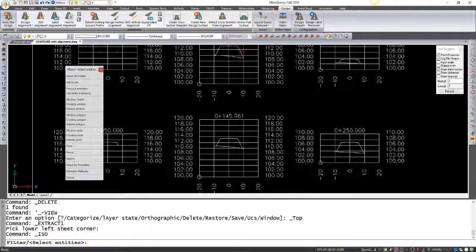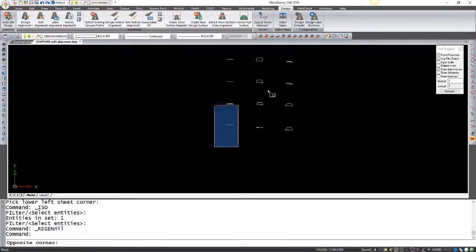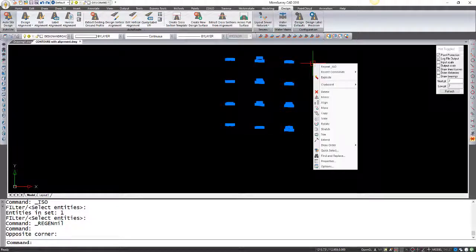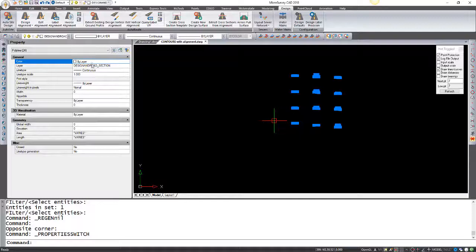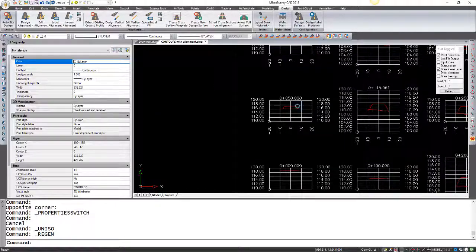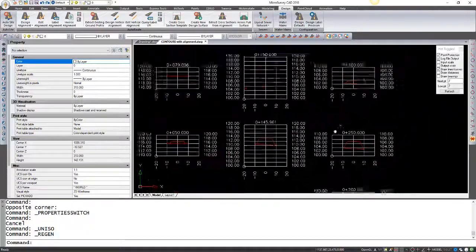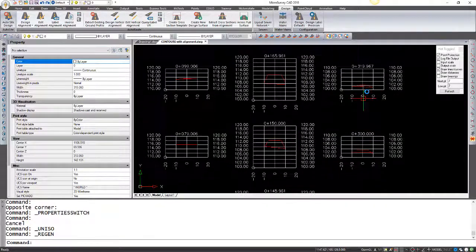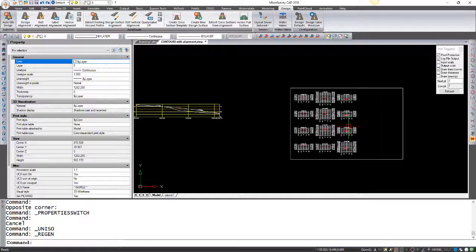Let me make the cross sections a little bit easier to see by changing their color to red. There you can have a look. If at any point you need to do end area calculations, you can just use the area tool to plot the area within them. And of course you can use these to check against your numbers and expectations.